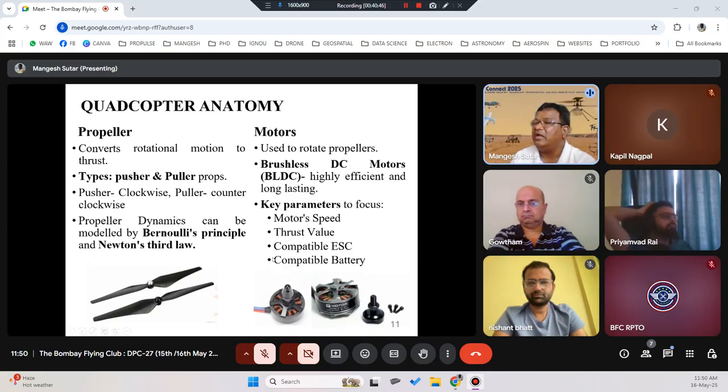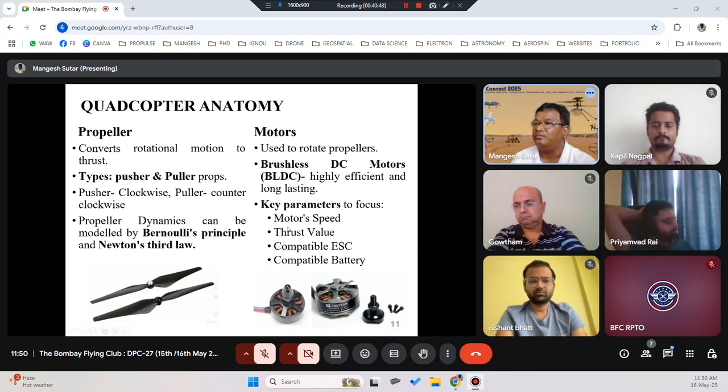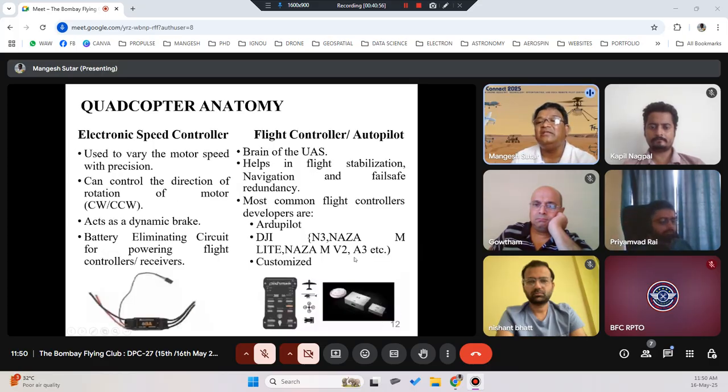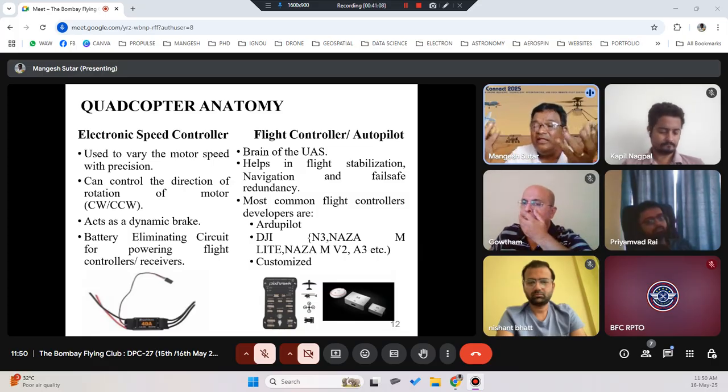Okay, that is how you will design your drone. So a compatible ESC is important. Based on the motor and the ESC, you will choose the battery. Again, battery is weight as well as power. So again, you need to balance it out. So when you are designing a quadcopter, a lot of things come into the picture. One is the structure, then the capacity.